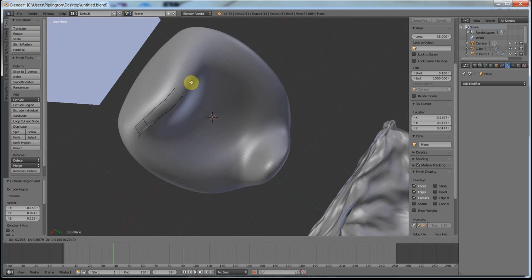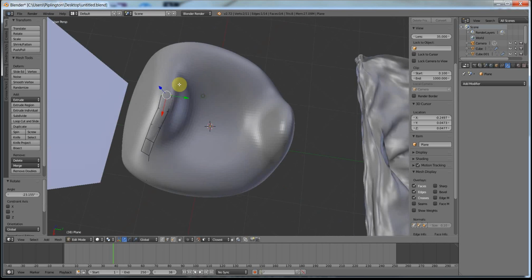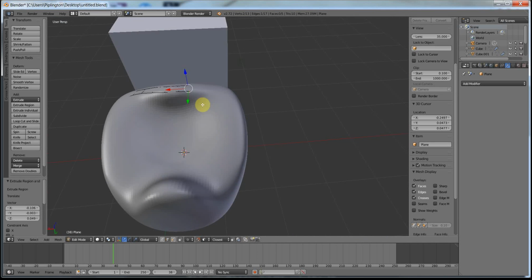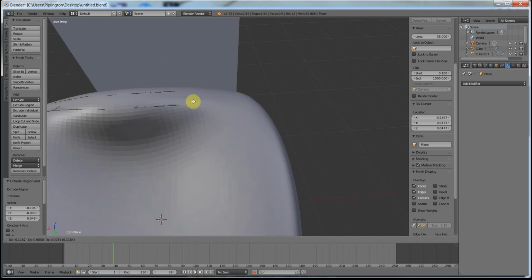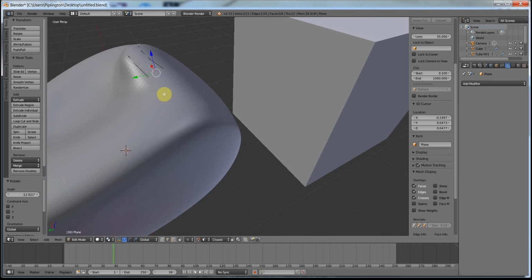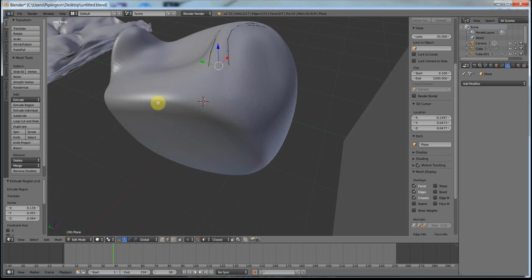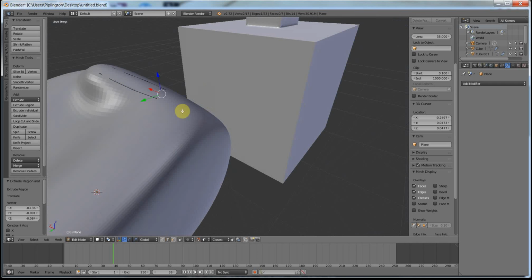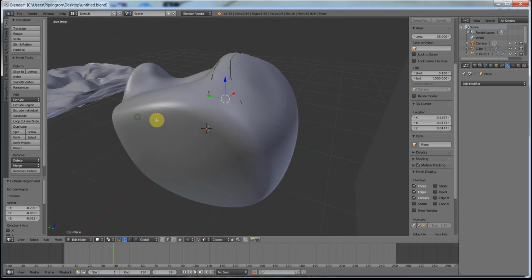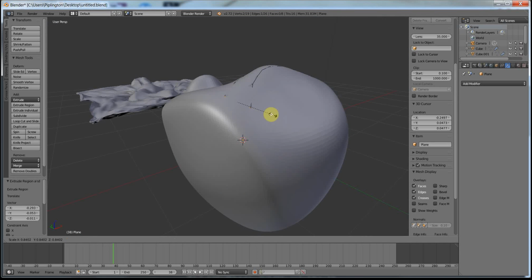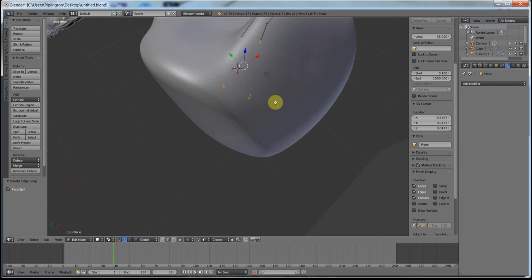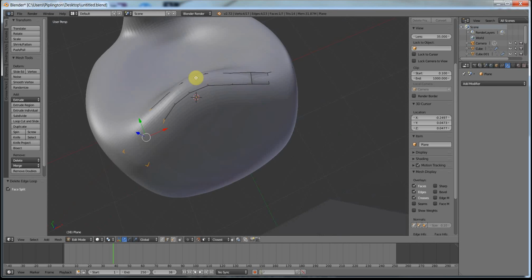And I'm just going to extrude over the top here, rotate a bit, extrude, extruding with E, by the way. I assume that if you're looking at making things into low poly, you know some modelling, but you don't necessarily know the techniques. And I haven't really focused on how low poly that is. We can always go in there and delete the edge loops just like before if we decide that we didn't want some of those loops.